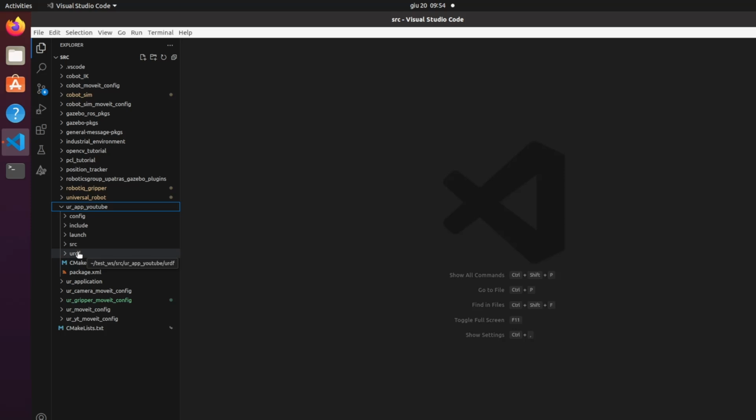We are gonna see what will be the configuration of the topic that this 3D camera contains, and then we will redo the universal robot MoveIt configuration, and then we will spawn our robots in a Gazebo environment with the MoveIt, and we're gonna see with Rviz, with the MoveIt plugin, what the camera actually sees, and we are gonna subscribe to the topic point cloud.